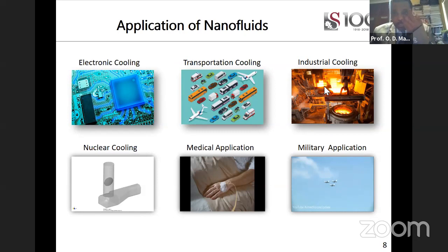Also, industrial cooling, you use nano liquid where you want to cast metal. When you want to cast metal, it's at very high temperature, and you want to shape it properly, you use nano liquid as well, to make sure that the cooling and the solidification of the metal is regular, and you control the cooling. The controlling of the cooling rate is where the magnetic field comes in, because you use a magnetic field to control the flow rate, the cooling rate of a system. Because the fluid that you use to cool is flowing across it, you can control the cooling rate. In industrial setups, they use this type of situation with nano fluid, and not only that, they use a magnetic field to control the cooling rate.